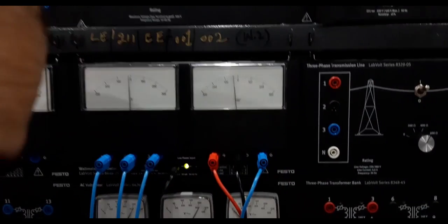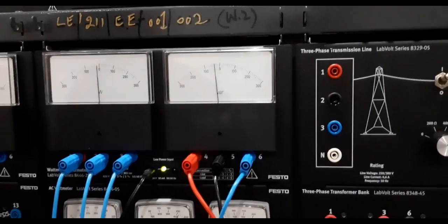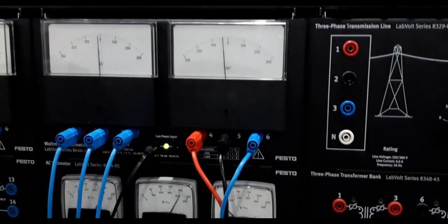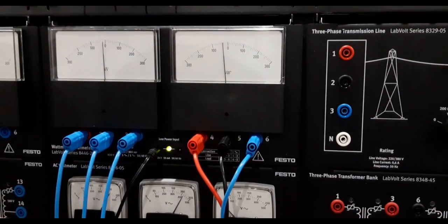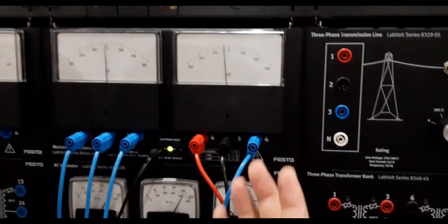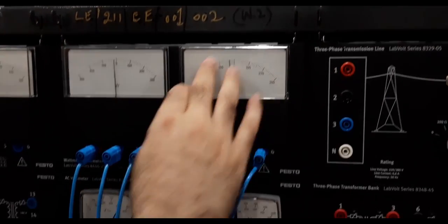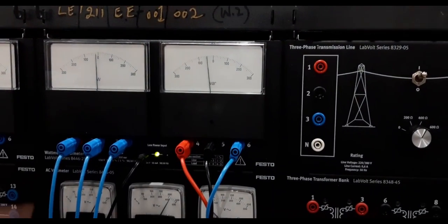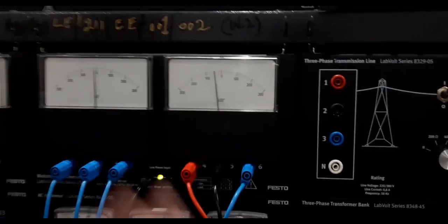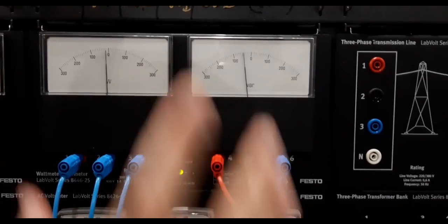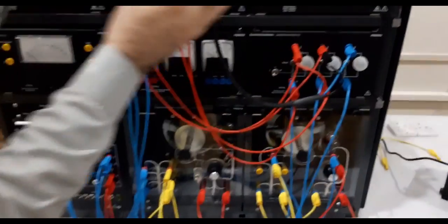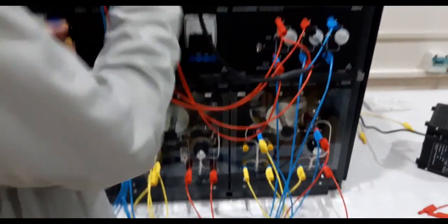If we make the excitation lower, meaning we keep it in the underexcited case, the reactive power is consumed. If we make the excitation overexcited, or if we increase the field current, then the reactive power is provided to the system. You see, if I increase the excitation, the reactive power is provided to the system. So now we have demonstrated the case of varying the field current before and after excitation. The reactive power changes only.